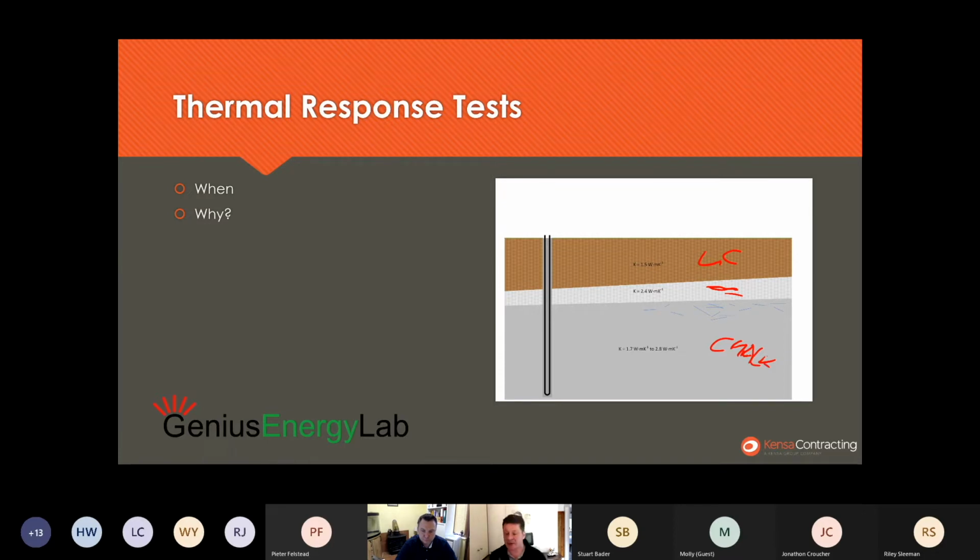The London clay is just what it says, it's clay. They actually dig this stuff up, they quarry it to be used as pond linings. So it's a malleable clay like you make pots with. The Woolwich and Reading beds are sands and gravels. Beneath that, you've then got the Thanet sands, which are a very fine running sand. It actually moves around. And then you've got the chalk.